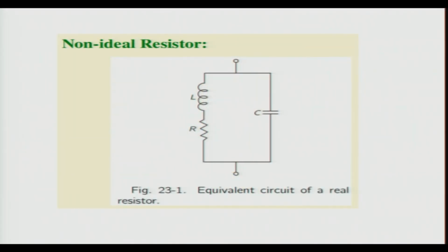If we actually take a similar kind of frequency response analysis of a capacitor or a resistor, can we go back to the resistors? Yeah. A resistor in fact also has such an equivalent circuit. In fact, we tried to do the frequency response of a 60 ohm rheostat, which is actually wound in a solenoidal fashion.